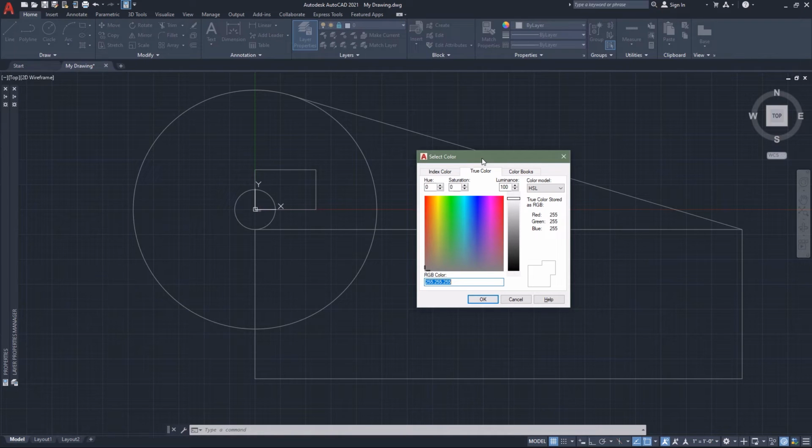Yes, the user can override the printer settings to print grayscale, but this can lead to much trial and error to obtain acceptable grayscale output. The use of true colors is best restricted to the production of graphically colored presentation documents or the occasional need and purpose for specific objects to print in color.